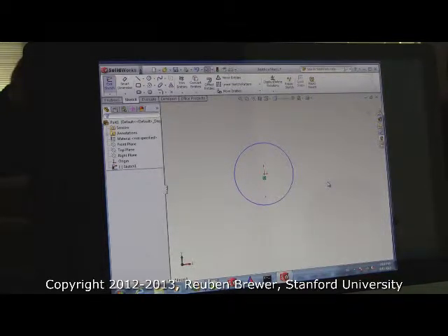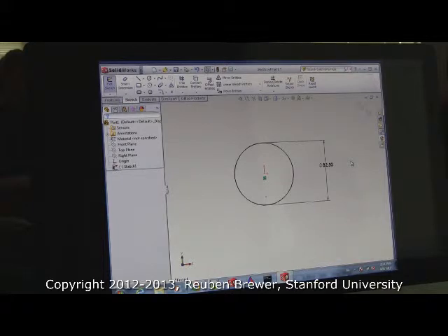In the end, for your part, all the sketches should be black. We'll go over why that is later, but basically things can change if they're not fully constrained, and maybe it'll only be a very slight change that you won't notice, but it'll be enough to screw up your robot. So go ahead and hit Control-Z. Control-Z does, in fact, undo things in SolidWorks.